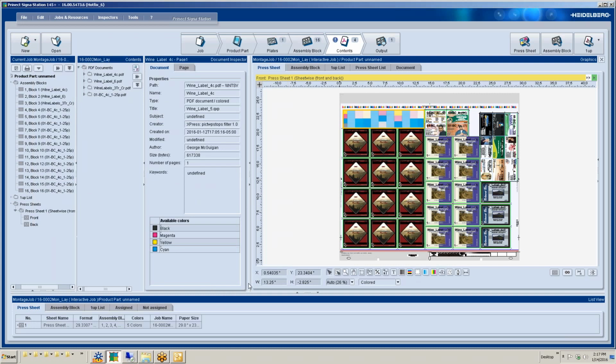The bar actually optimizes based on the artwork within the document. Look what happened here. We've got darker and lighter shades of cyan for a balanced ink pickup. The artwork has enough magenta, enough black, enough yellow in most areas. Where we need the most help is in that cyan. So you can see where that's being laid down per zone.